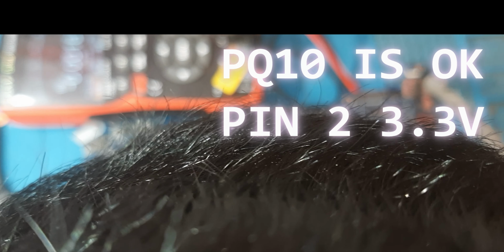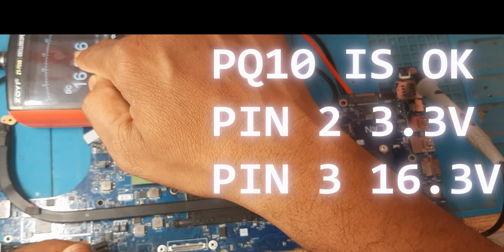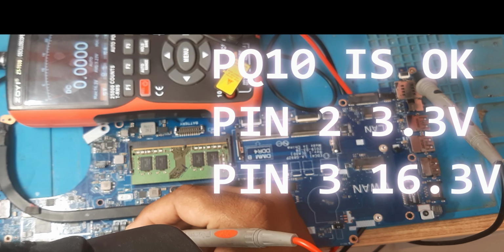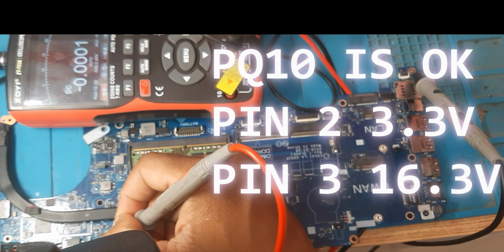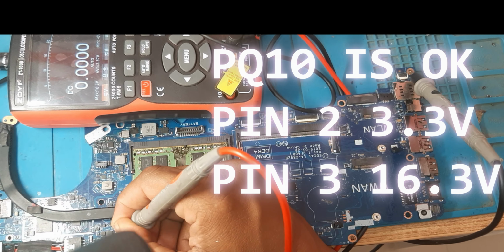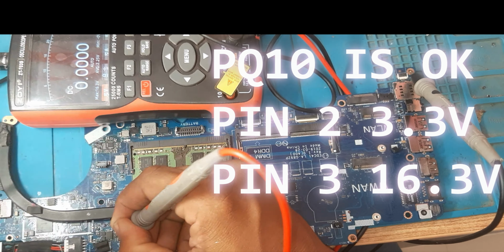See pin number 3. Yes, it has 16.3 volts. But what about pin number 4? Already ground. Ground. 6, there is no voltage. 5, there is no voltage. Once again 5. Carefully we need to check, it's no voltage. Okay, only 2 pins have voltages.